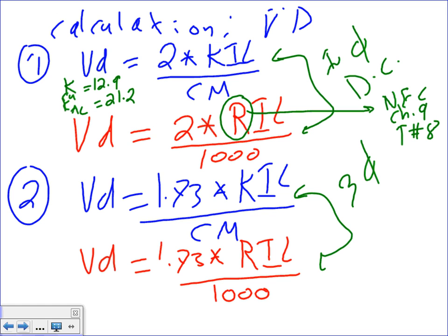Table number 8, Brad, I know you asked the question is, why divided by 1,000? Table number 8 gives you the answer in kilofoot. The number that you see in table number 8, which I'm going to show you now, these are in kilofoot. So in this formula, all you have to do is grab the number from that table, and you don't have to worry about dividing it by 1,000. Why? Because if you slot this number right in here, it's already divided by 1,000. The number that you get from the table, like if you find 0.23, is for every 1,000 feet, always given in 1,000 feet.